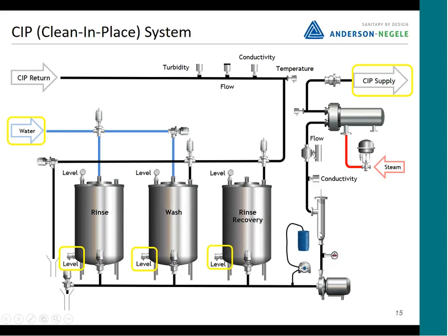All right, so let's get to the instruments. I promise you we're going to talk about the instrumentation here. So we're going to put some level sensors in these tanks. It is not uncommon to have point level switches in CIP tanks, and a point level switch is going to turn the fresh water, right? Fresh water coming in here, it's going to turn it on and off,